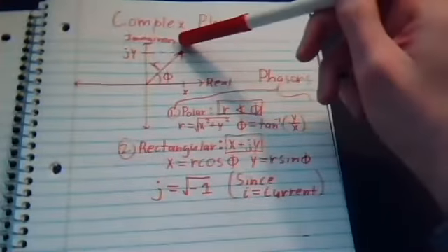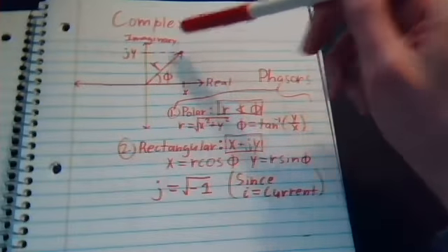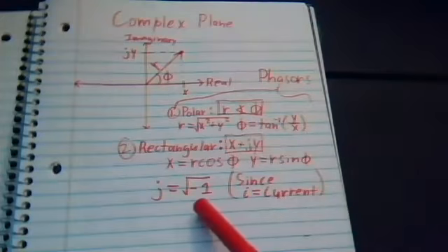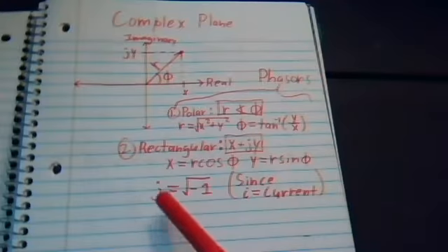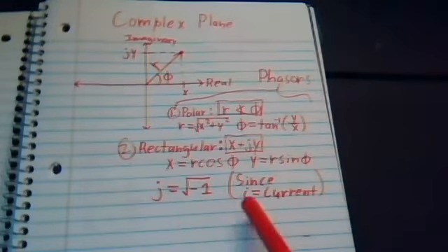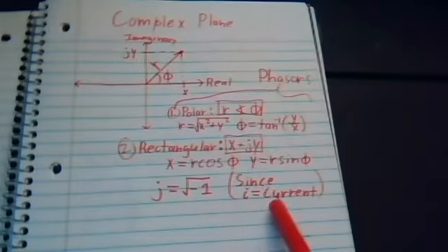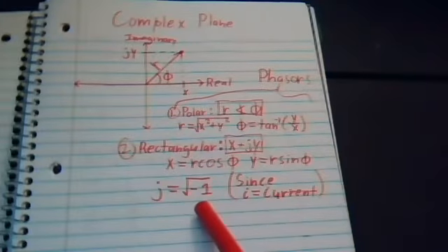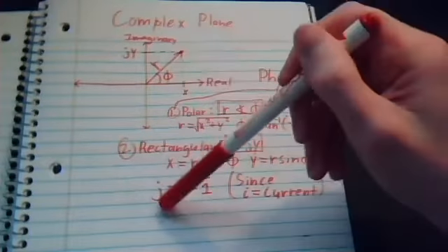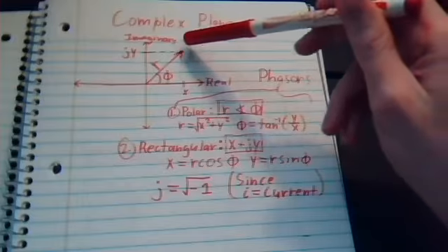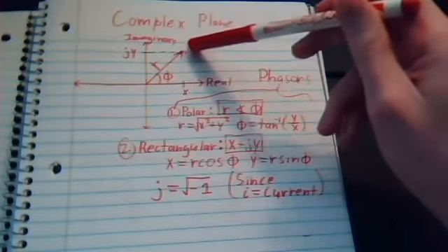And when we say imaginary, we mean the same imaginary number i that you learn in pre-calculus, where we define it as radical -1, but instead of being i, it's going to be j here. The reason for this is because i is current, so we can't use i to represent the imaginary number negative radical 1 anymore, because that's been taken. So instead, we say it's j. And to represent a point on this complex plane is really describing a phasor.